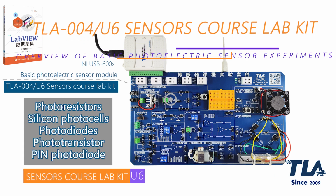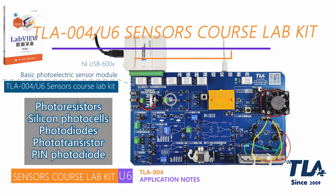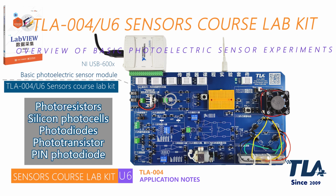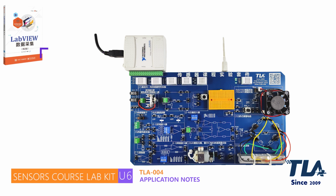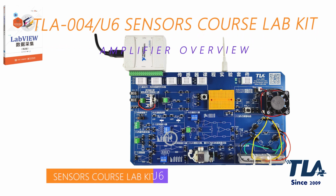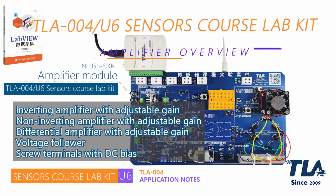Module 1 is an experimental module for measuring the characteristics of 5 basic photoelectric sensors. The 5 basic photoelectric sensors are photoresistor, silicon photocell, photodiode, phototransistor, and PIN photodiode. The experimental module provides the measuring circuit, high illumination light source, and supporting light source control circuit required for the experiment of 5 basic photoelectric sensors. During the experiment, the complete experimental process control of basic photoelectric sensor characteristics can be easily realized by combining the experimental software DAQware for NI-DAQ-MX.